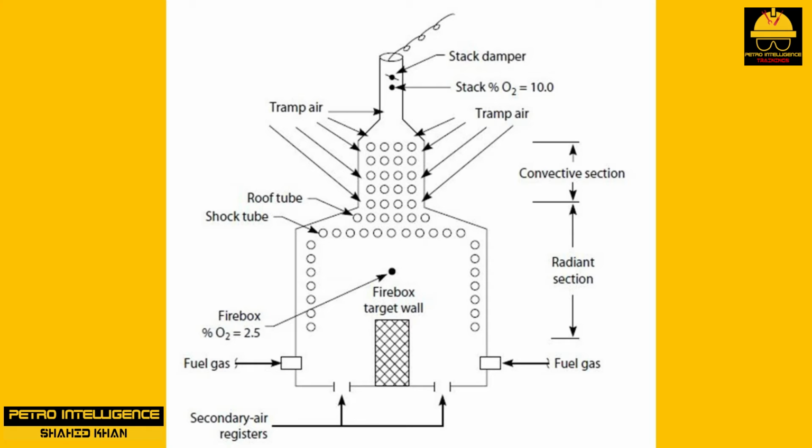Oxygen content field measurements should always be taken with a single portable oxygen analyzer. Be careful to calibrate the portable instrument for the range in which we want to use it. Cylinders of test gases with specific oxygen contents are available for calibration purposes.